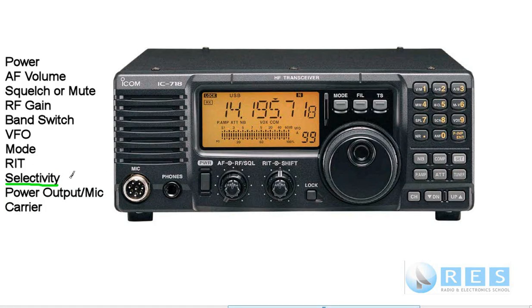So if you're a real keen Morse code operator, a CW operator, you would have a crystal CW filter fitted to your radio. You have an SSB filter, 3 kilohertz wide, already fitted to your radio, and some radios have multiple filters for different modes fitted to them. Others, when you buy the transceiver, the filters are an optional extra from whoever you bought the radio from, and you have to fork out some money to be able to plug them in.